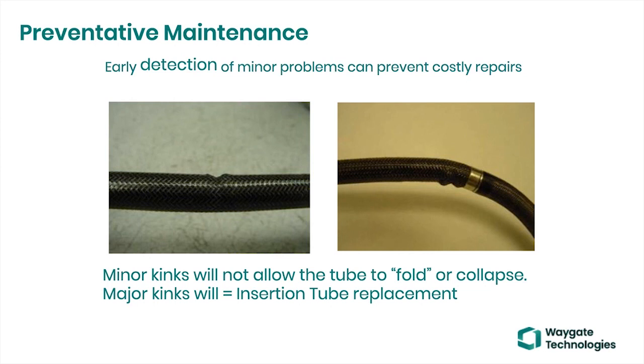Inside there are stainless steel monocoils. That stainless steel monocoil is crushing the internal camera harness and or the internal light harness, and or it's crushing the articulation cables. And so, Tom, to that question that was asked, on the right of that ferrule, there's some mesh that allows the articulation to happen more fluidly. And inside of that is a rubber Viton sleeve.